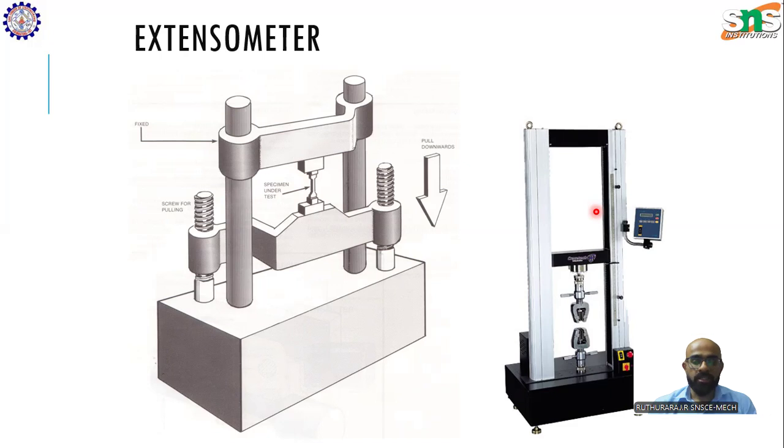Here a concept can be related. In a ductile material, first there will be elastic deformation, then plastic deformation, then ultimate tensile strength. After that, it starts to undergo necking. The material will actually be elongated, and after necking, it will fracture. Whereas if you take a brittle material, there will be only elastic deformation, limited plastic deformation depending upon the brittleness of the material, and then there will be no necking. Fracture is the ultimate thing.